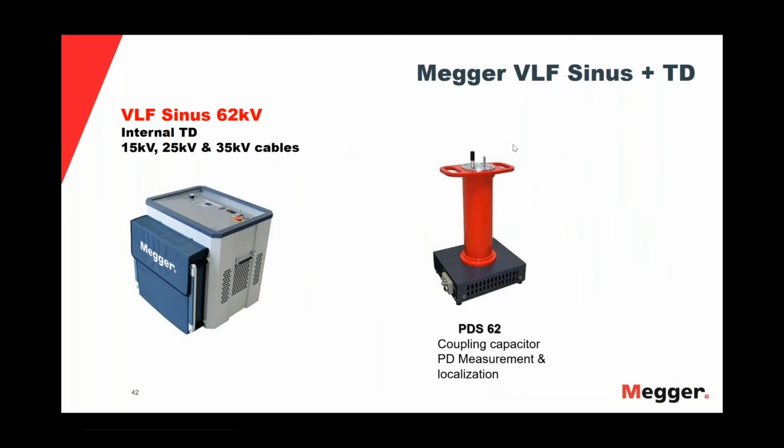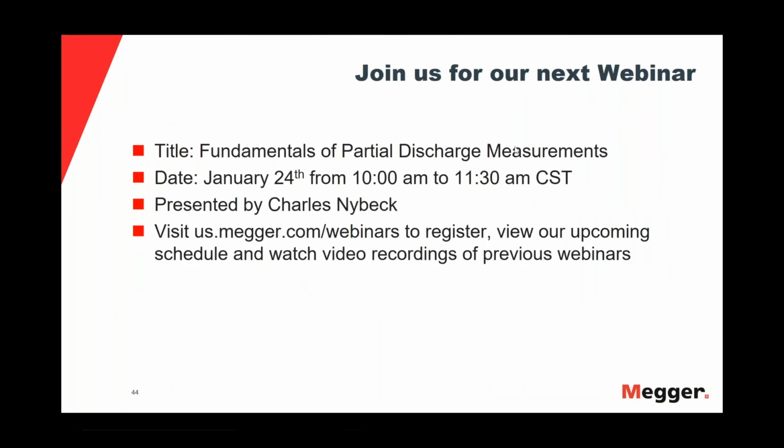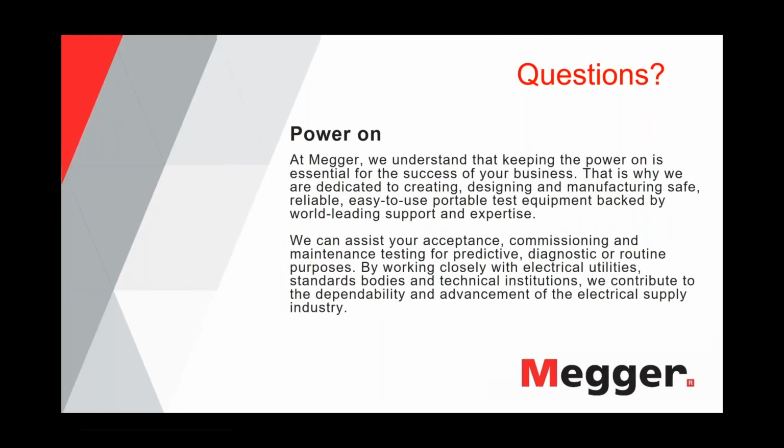Okay, so I hope I understood this correctly and everybody can hear me. For commissioning new cables, as Javier pointed out, the tan delta measures the aging condition of the cable. If you have a new cable, there is no aging, okay? And so the test is actually pretty ineffective on new cables. You will not measure anything, and what you measure, you expect that it is pretty low. And since the standard, as Javier also pointed out, has this traffic light philosophy, it's also not really necessary to have any sort of fingerprint or whatever.